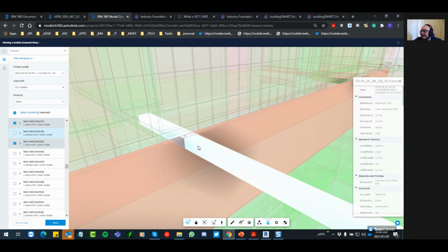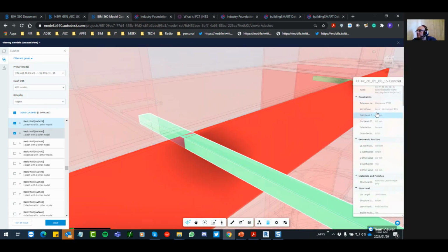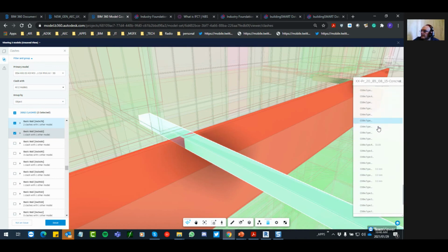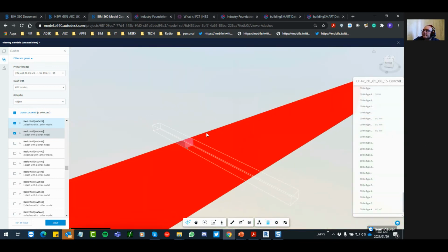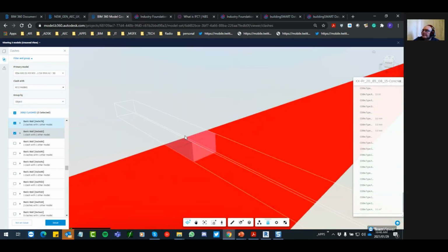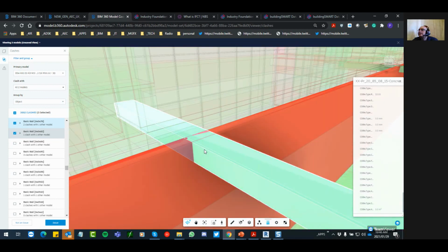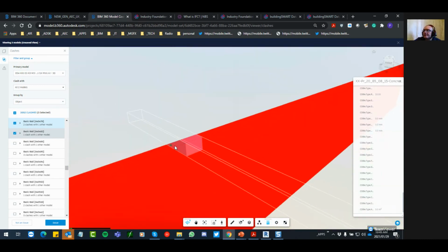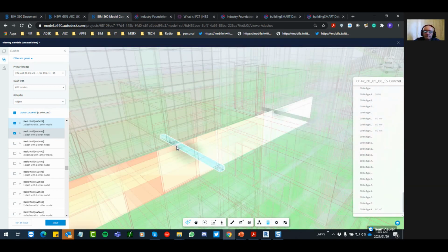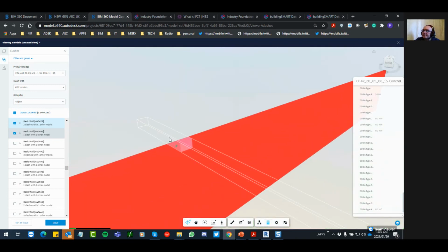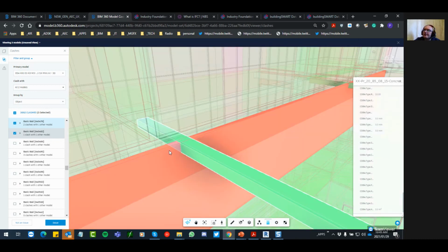And if you click on this element, you can even see the information that you are recording against that object. So this is between a structural model and an architectural model, and there you can see how the beam is impacting the wall, and so we would like the architect to go and cut that out of his profile. So this is very useful. Especially important also with ducts and structural walls, but that we can do between the models, and once it's set up, it happens automatically. So that's wonderful.